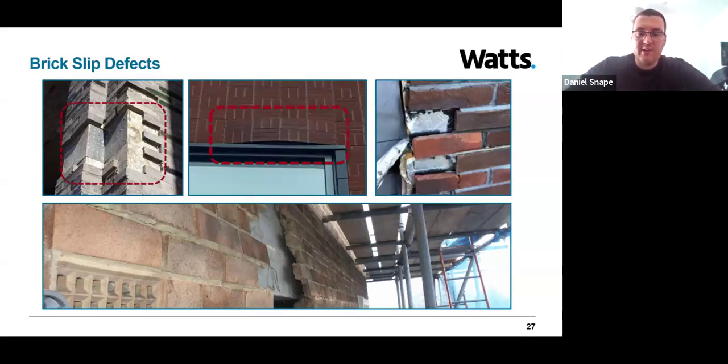Now, the CWCT, the Centre for Window and Cladding Technology, if I've got that right, also clearly requests in their guidance that extreme caution is exercised around the use of bonded brick slip connections, for the reasons I've just set out. If a brick slip falls from height and hits someone at ground level, the results can be pretty catastrophic, and nobody wants a claim against them or their company in that instance. So it's important that caution is taken.